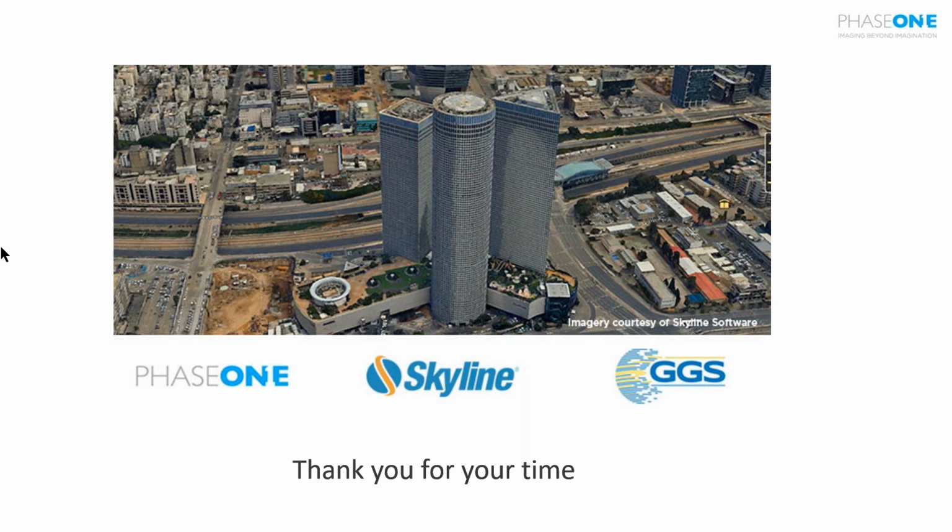Does the use of LiDAR help in the mesh generation? Yes. Does it have to use trajectory data or a LAS file? We don't need trajectory data. We can use just a standard LAS point cloud. What we do is compute the trajectory by comparing the LiDAR point clouds with the image-based point cloud, and we create our own trajectory for the LiDAR points to be able to establish the normal vectors for the surface creation.